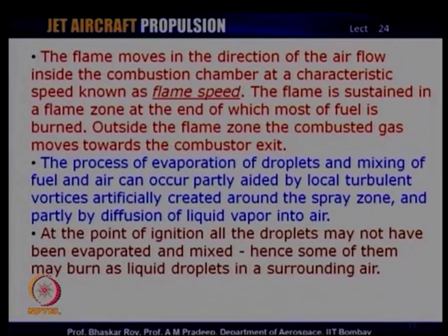The process of evaporation of the droplets and mixing of the fuel and air can occur partly aided by the local turbulent vortices, which are artificially created around the spray zone, and we shall have a look at this phenomenon in the following slide. At the point of ignition, all the droplets may not have been evaporated and mixed, and hence some of them may burn as liquid droplets, as I mentioned in the last slide.